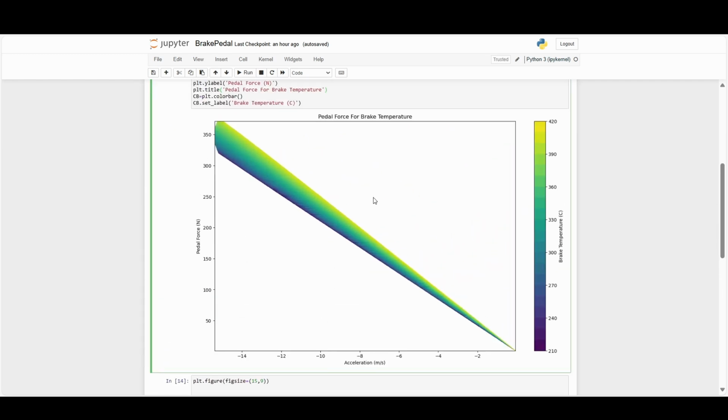So if you didn't want to change your brake rotors or anything else, or if you don't have a brake bias adjustment in the car, then you may consider, or I would definitely consider for this specific example, different front and rear brake pads. So they have different coefficients of friction based off the temperatures that we're expecting to see.